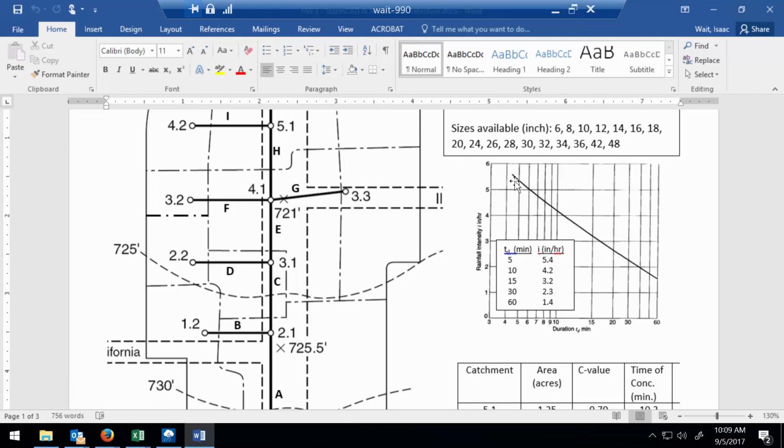But for a short duration, there would be a really high intensity. Part of the reason why it can't maintain a super high intensity for a long time is that the clouds are moving. You can have a concurrence of lots of clouds over a high elevation, a big depth of cloud coverage, only momentarily. It would be more common for the depth of the atmosphere that's experiencing precipitation to be narrower, and so more spread out. That's part of the reason why intensities are low for longer durations.